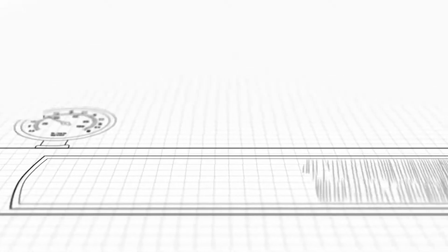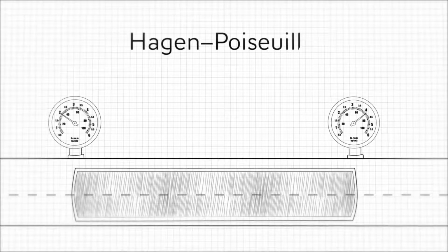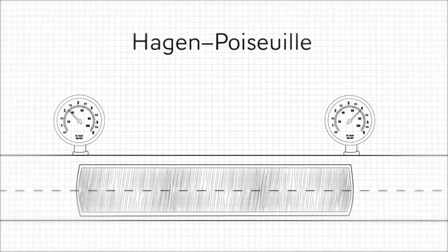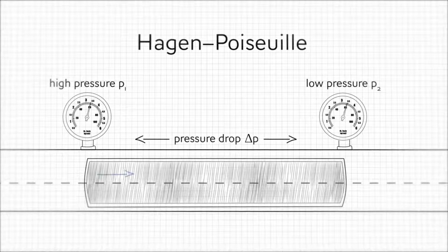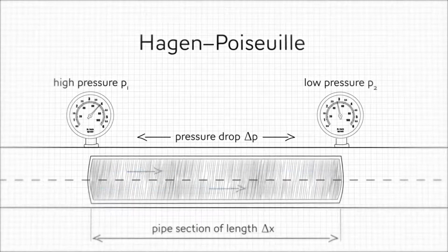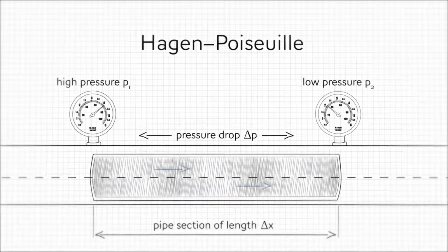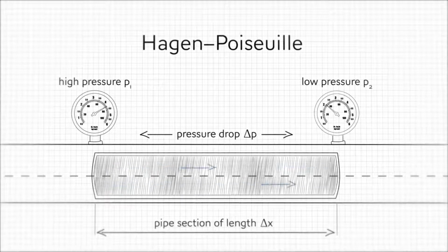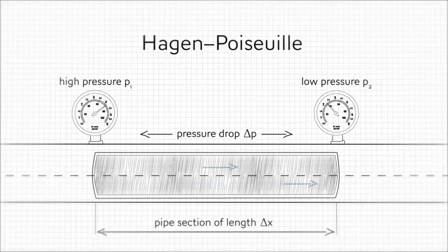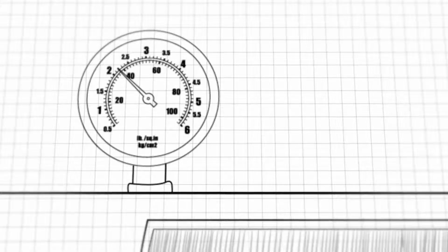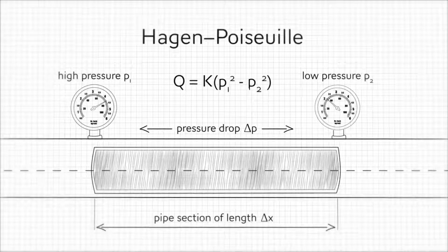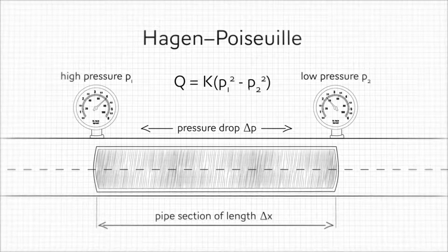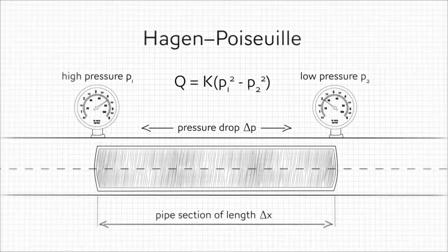Pressure-based mass flow controllers are based on the Hagen-Poiseuille equation. This physical law describes the pressure drop in an incompressible fluid with a laminar flow through a long cylindrical pipe of constant cross-section and can also be extended for use with compressible fluids or gases. By measuring the upstream pressure and downstream pressure across a laminar flow element, this equation can be used to relate these measured pressures to the actual mass flow.